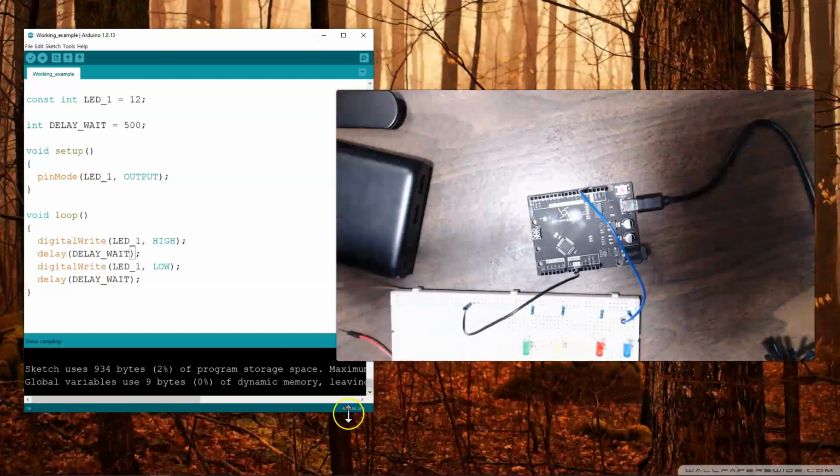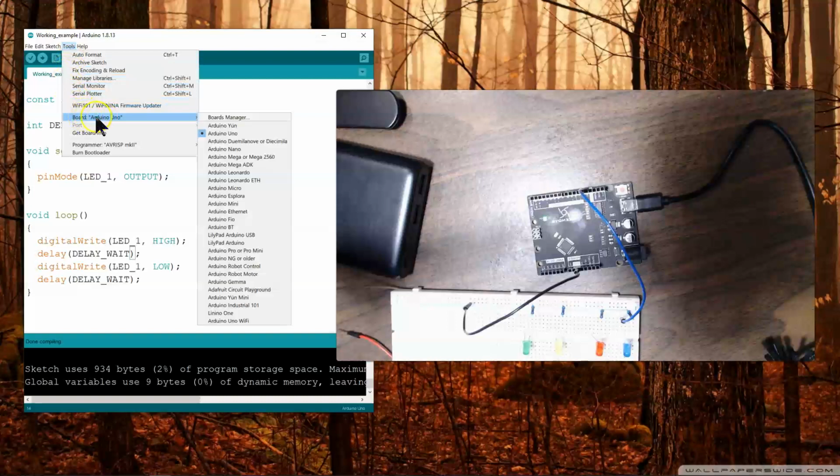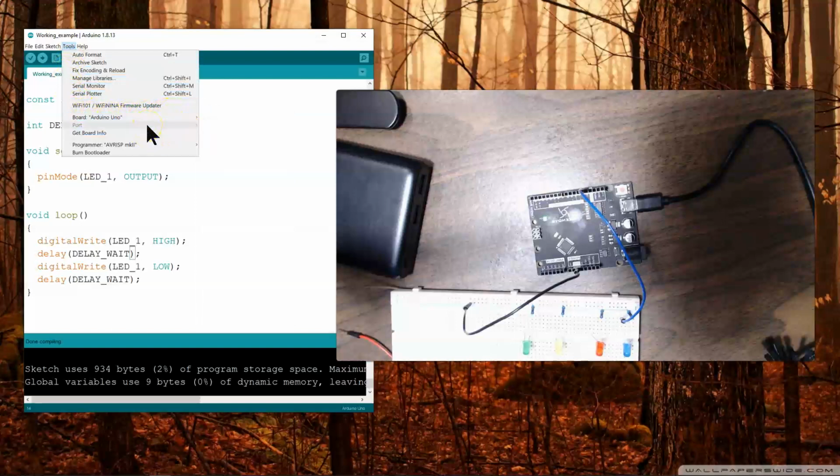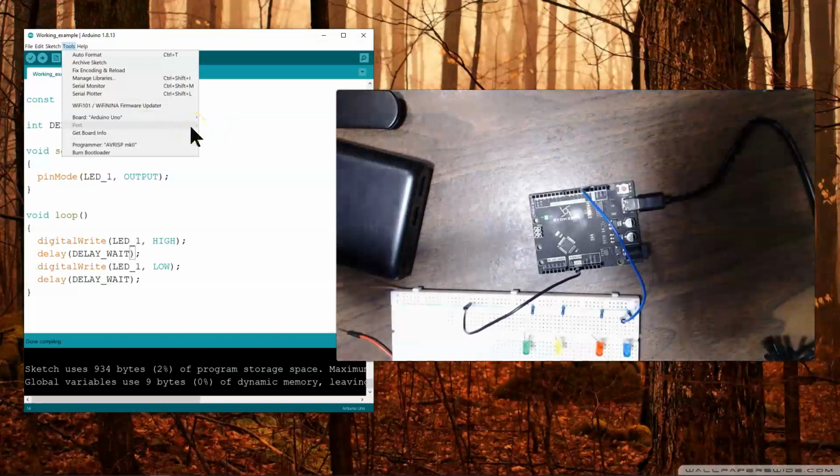So the first time you plug in your Arduino, you want to make sure everything for your sketch is set up properly. You don't have to keep doing this, but it's something to check if something's going wrong with uploading. So this is where you want to go to Tools first, and then select Board. By default it says Arduino Uno, because it detected that, so you're okay. So I'm just verifying, hey, it says Uno. Next is to know what port it's actually connected to. This is not letting me select it, so I'm hoping that everything is actually okay.